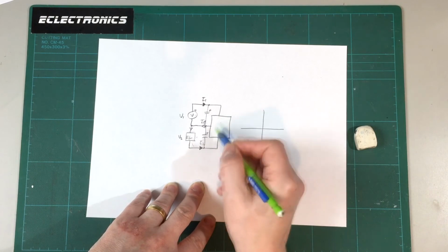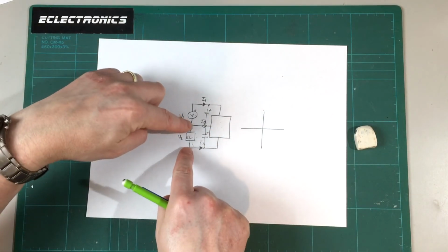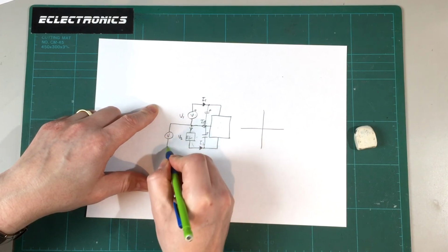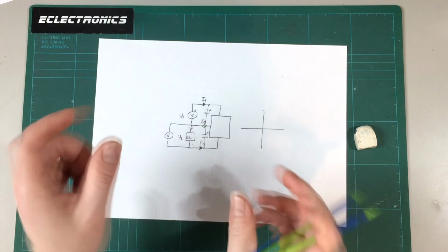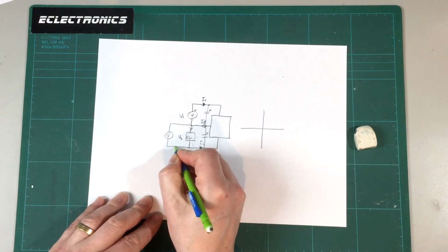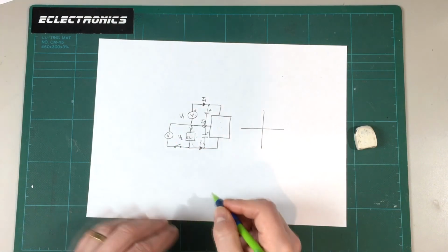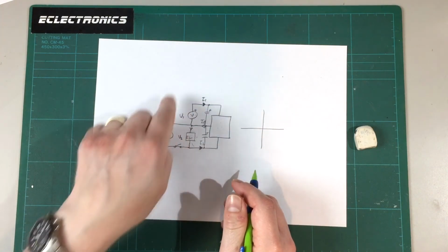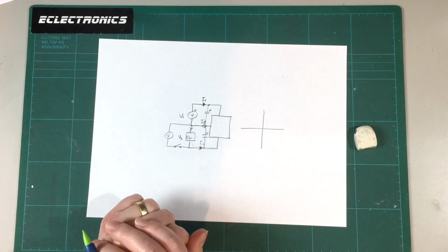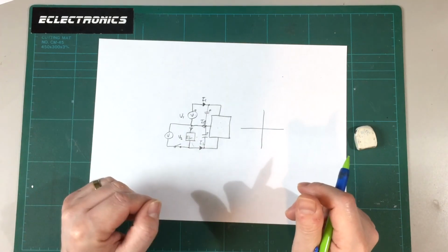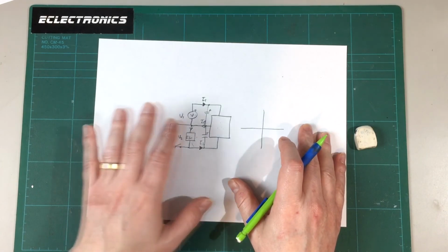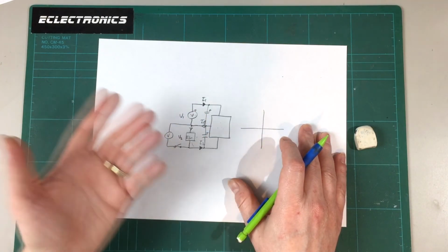I may need to persuade this circuit to wake up by actually having a power supply on this half as well to start it up, so we may need to have another one here so that we can get the scenario where it looks like two batteries are connected and they both have potentials on them, and then when we start the test we disconnect the second power supply. Once current is being dumped into the electronic load, we can just turn that off, plot our characteristic, and off we go. It's going to be interesting to see if we can make it work, but I think this is going to give us the data we need, and it's going to allow us to compare the different types of charge balancing circuits that we can get our hands on.